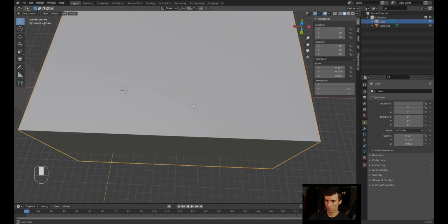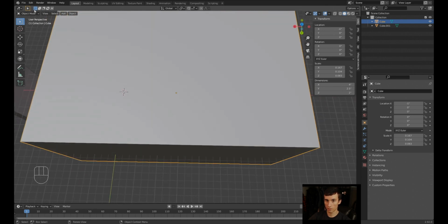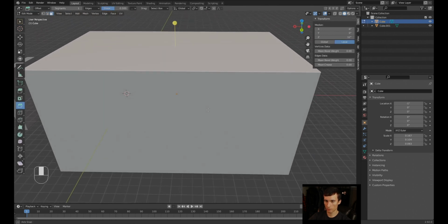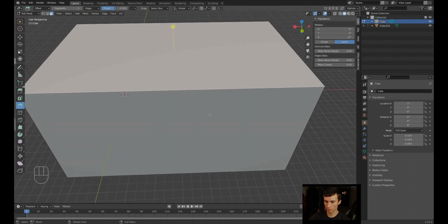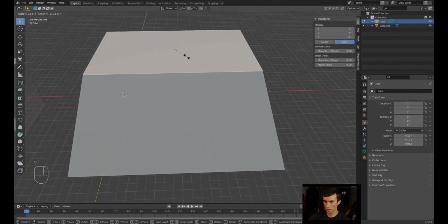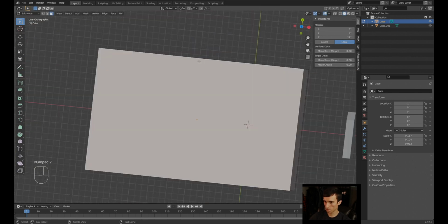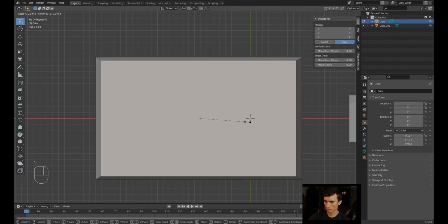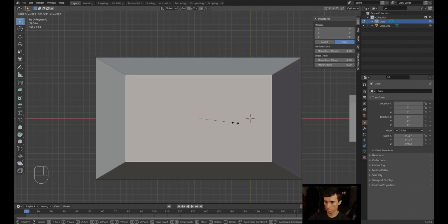And now we're gonna scale this top face. Edit mode. Select this top face. And we're gonna scale it. So S. We'll select that so that little bubble's not there. This one. S and get it down and scale. Press 7 to look down on the object. S. And there we go, we're making the pyramid now. And just gonna guess the size.